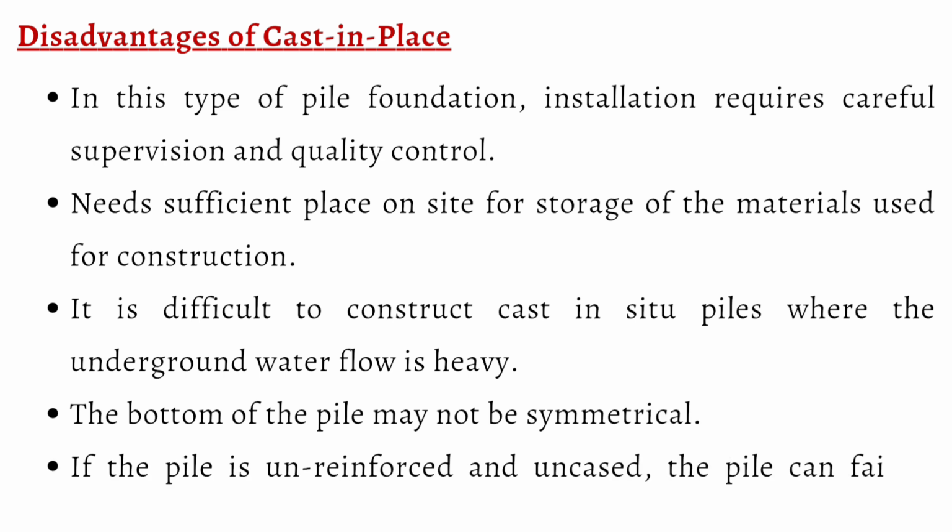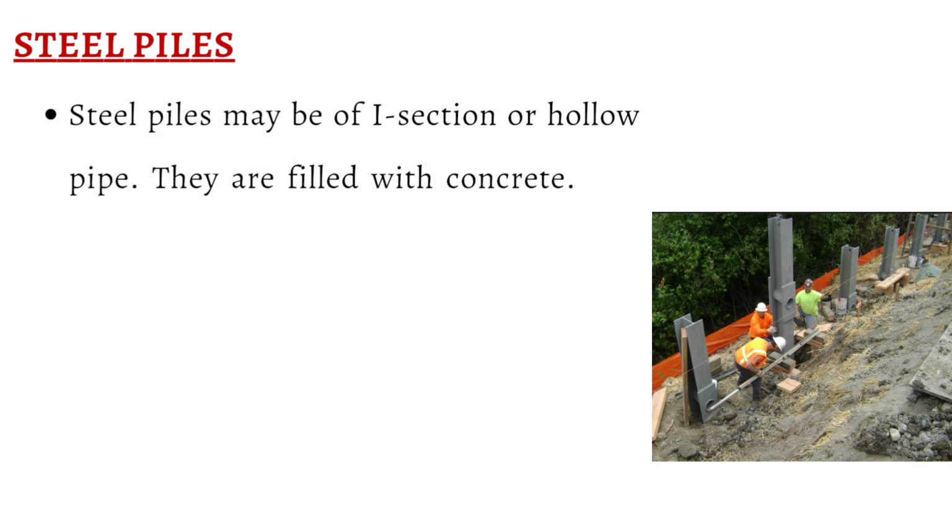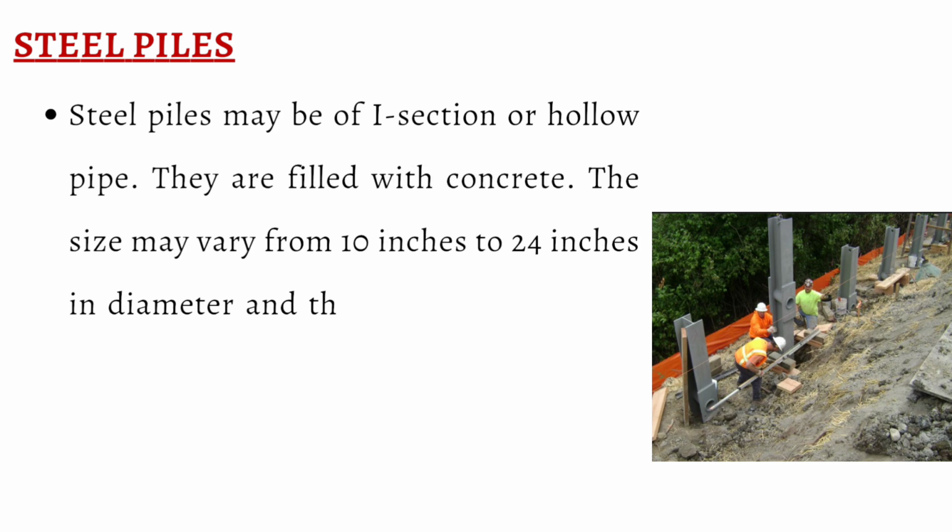Advantages. The shells are lightweight, so they are easy to handle. The length of the piles can be varied easily. The shells may be assembled at site. No excess reinforcement is required, only to prevent damage from handling. No possibility of breaking during installation. Additional piles can be provided easily if required.